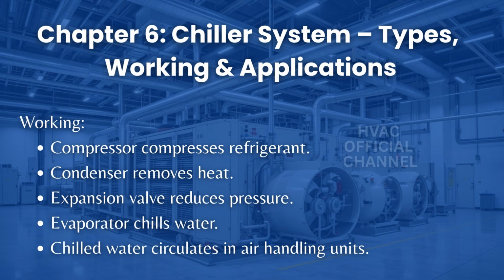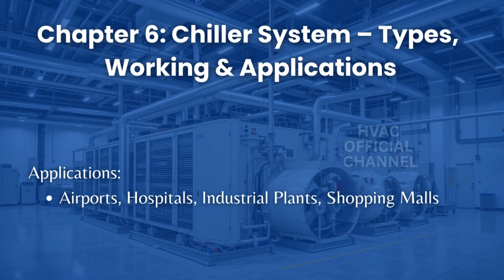Working. Compressor compresses refrigerant. Condenser removes heat. Expansion valve reduces pressure. Evaporator chills water. Chilled water circulates in air handling units. Applications: airports, hospitals, industrial plants, shopping malls.